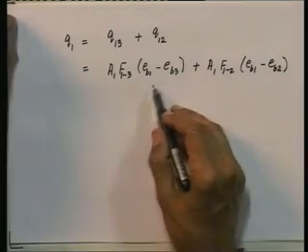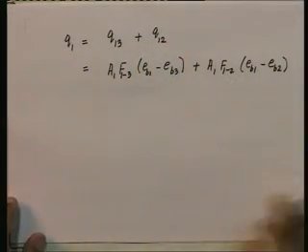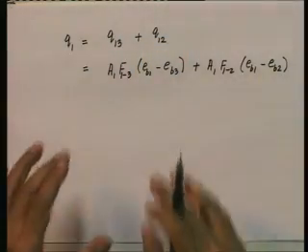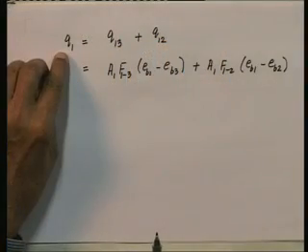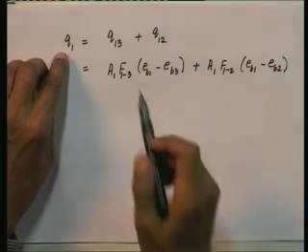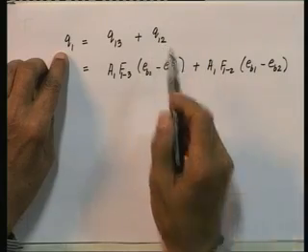I am writing EB1, EB2 and EB3 instead of writing everywhere sigma T1 to the power of 4, sigma T2 to the power of 4 or sigma T3 to the power of 4. That is really what EB1, EB2 and EB3 represent. Instead of keeping on writing the bigger expression, I will write EB1, EB2, EB3. At the end, I will substitute the Stefan-Boltzmann law. All right. So, the rate at which I supply heat at surface 1 must be equal to the heat exchange rate between 1 and 3 and the heat exchange rate between 1 and 2.